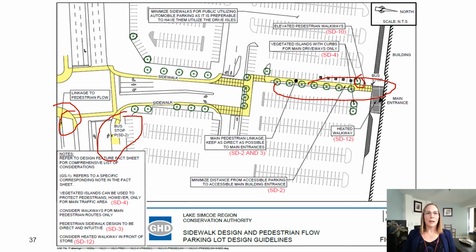and just using the salt to melt the snow. Snow storage locations for walkway clearing should be located to prevent meltwater draining over the walkway, similar to with the snow piles in the last few slides. And then walkways should be properly graded to promote drainage as well and minimize refreezing. You could also consider different materials. You could have rough materials to add traction or dark materials to promote solar heating. And then another option is the use of heated walkways in front of the building, which could be considered to limit the amount of salt applied, and it would also limit the amount of salt going into the building. So these would mostly be considered near building entrances.